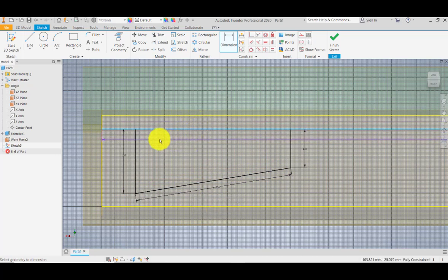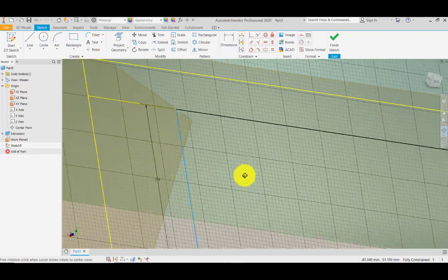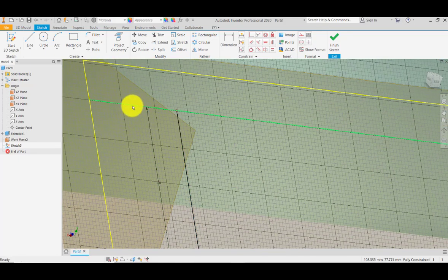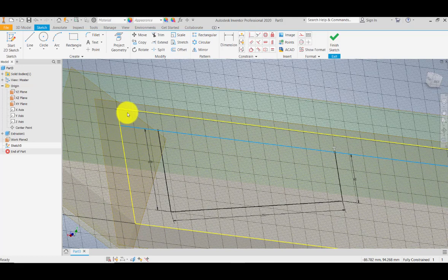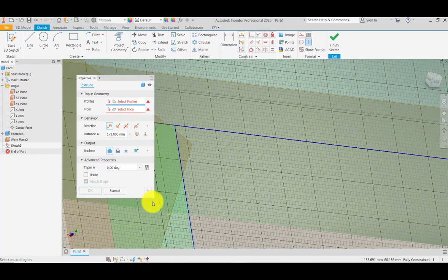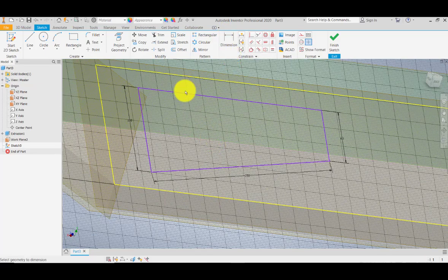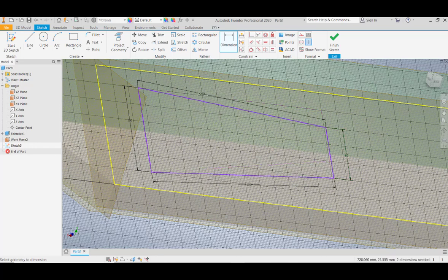And for this one, it's already checking the other side. So it's projecting. Let's try to adjust this one. This is already projecting the lines, so I want to delete this line. I'm not needing this one. Oh, wrong keyboard entry. So I will be deleting that one, I don't need that one. So I will be giving the dimension for this one. This is 246, so I'm going to give it 250. I'll make it a whole number.